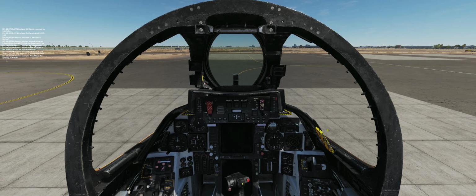Select fire dead X on master test selector and verify left and right fire go lights illuminate. Next item, select INST on master test selector and verify that engine, fuel, wing sweep, and alpha instruments are working. Arm ejection seat. Close the canopy.